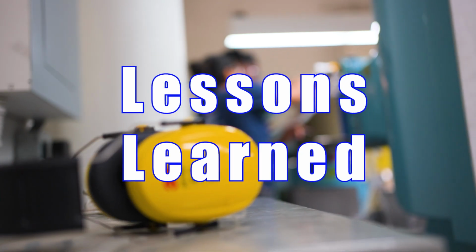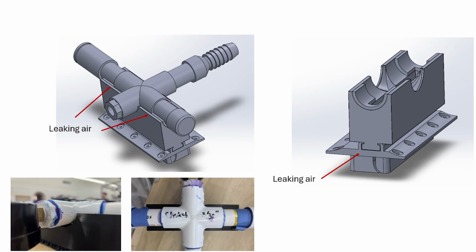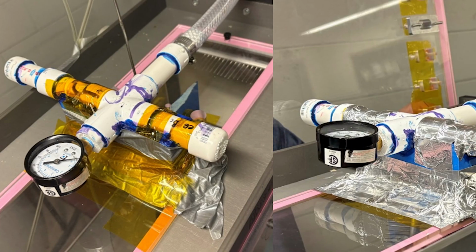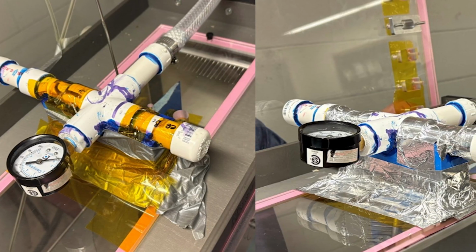The primary challenge we faced was having unwanted leaks in the system. We were able to reduce them but were unable to make it completely leak-proof while maintaining the modular design. Improving the mating between the injector and SFS, potentially by transitioning to a permanent fixture, could eliminate leaks and maximize total pressure.